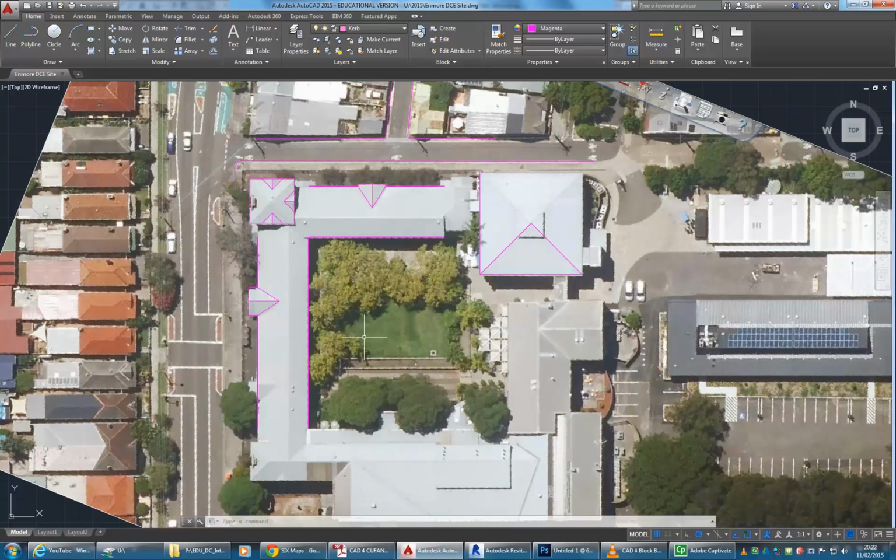Yep. Is that still a roof line or is it just become the outline? Yeah, it's just the two sets of 2D lines, but then we can generate 3D forms from that in Revit. So why did you do the roof? Oh, because for the parts that we're not going to model up. You won't want to model all of it in Revit, but it'd be nice to have the whole building shown in your site and other drawings in Revit, and so you can just turn those lines back on for that.